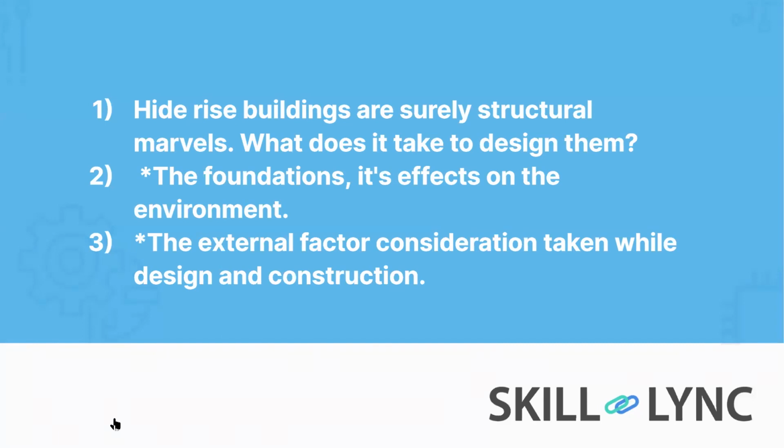And one of the reasons why they do this is to reduce the wind load, because the wind force is higher at the top. So as you reduce the area of the building or surface area of the structure, the wind load acting on this building is going to reduce as well. So that is one way how they reduce the wind load. There are also other ways where they provide open floors at certain levels to allow the wind to pass through.